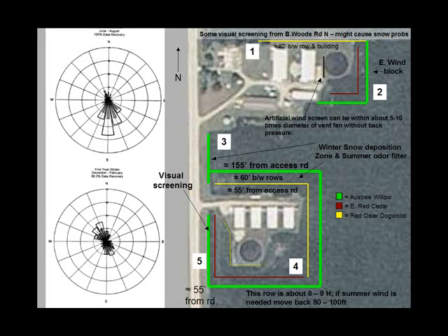Here's what we call a wind rose, and this is for the summer months, June through August in central Iowa. This is the winter months, December through February in central Iowa. And the bigger this is, the higher percentage of the prevailing winds are coming from this direction. So in the summertime in central Iowa, by and large, winds are coming from the south, the southeast, and the southwest. In the wintertime, it's just the opposite. It's coming in from the northwest, the north and northwest primarily. Got a little bit coming in from the south, but most of it's up here.